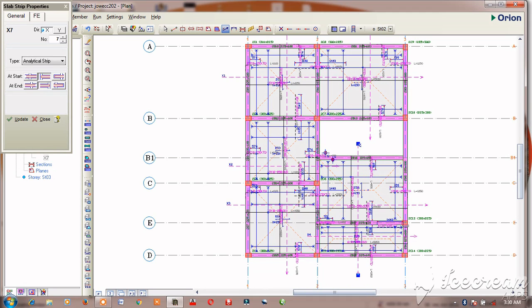click it here. So all my slabs are all sufficient in depth and in deflection. In terms of deflection, they will not deflect. So I use 150 for them. But if it happens that your slab is insufficient, what we only do is that you will just change the depth of the slab by clicking it.